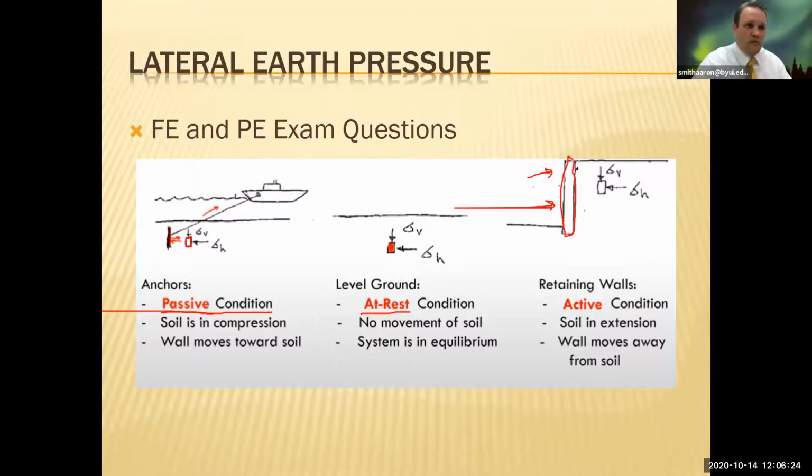Now you can imagine, on the other hand, like that iClicker question we just showed you, there was a picture of a wall. It had some layers of sand in it, a water table, and even a big surcharge up here, and all those loads are acting on the soil. You can imagine it's trying to bulge and push that wall over, almost knock it over because all those forces are acting. Soil doesn't want to stay square like this. If you've driven by a construction yard with big aggregate stockpiles, the soil wants to sit at its angle of repose, which is very similar to its internal friction angle. So soil doesn't like to be in these square shapes. Mountains are not square shaped. Mountains typically are shaped like the pyramids, and that's the state the soil wants to get to.